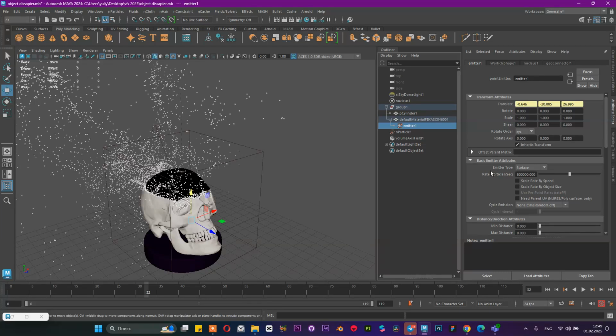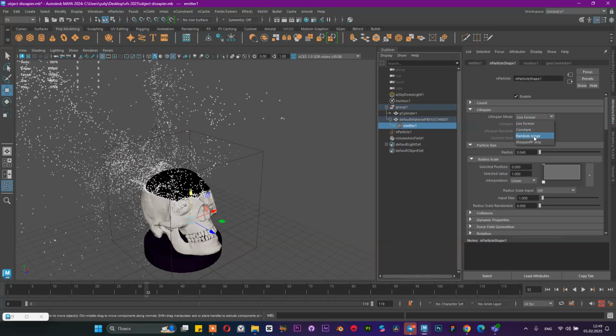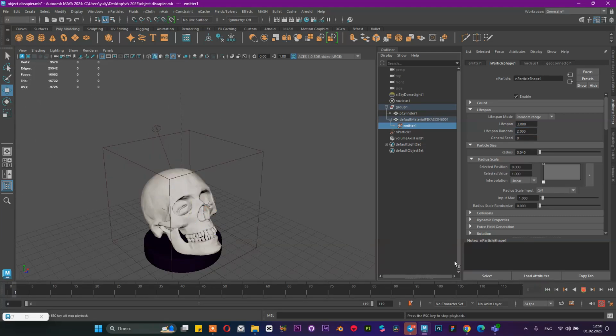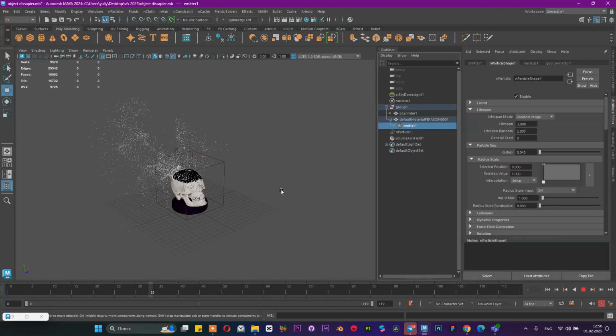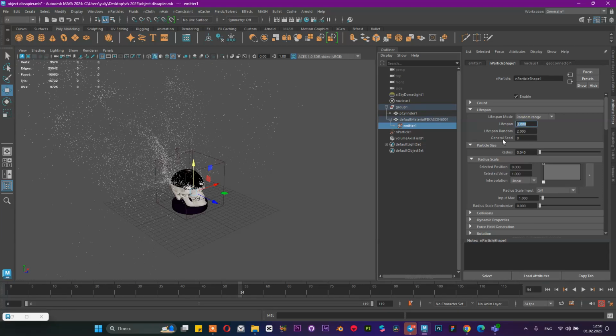Now we didn't switch off the particles rate. We are going to change only random range for this lifespan and check maybe from 3 seconds to 2 seconds. And let's see how it disappears. Maybe more, maybe less. One and 1.5. Let's save.